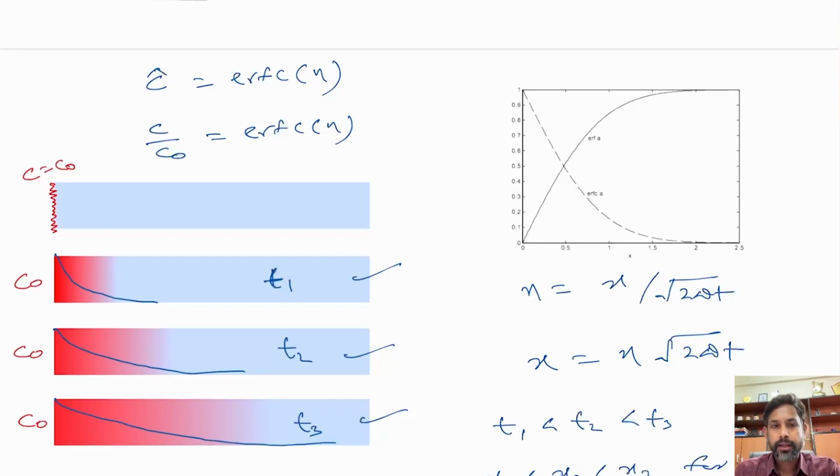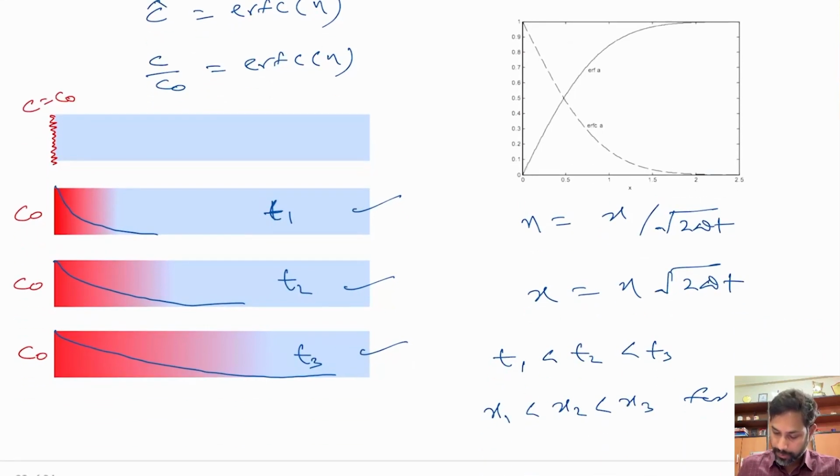All right, so this solution that we have derived is for diffusion in one particular dimension, while we are maintaining a constant concentration at one boundary. But depending on different conditions, let's say you are solving a two-dimensional or three-dimensional problem, this may have different solutions, but in most cases we see a diffuse interface between one fluid and the other in the case of miscible fluids. As you can see, the concentration is neither 1 nor 0, but the value goes from 1 to 0. And this diffuse concentration usually decreases in the form of an error function at the interface, as you can see here.